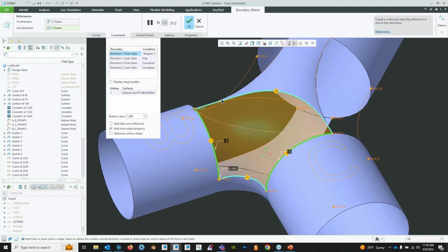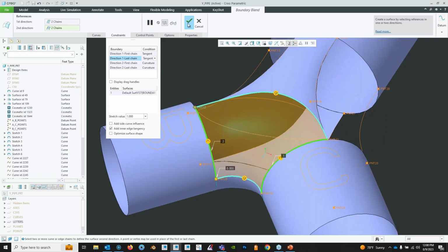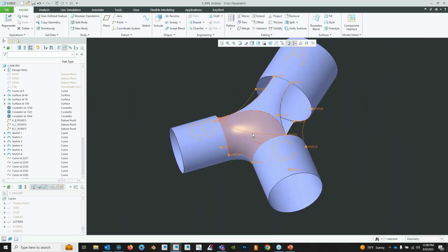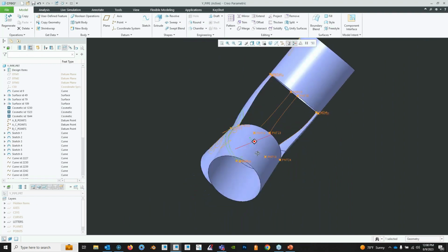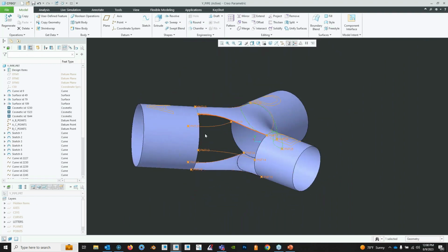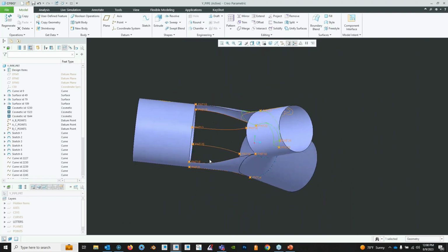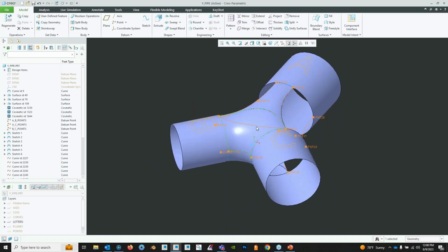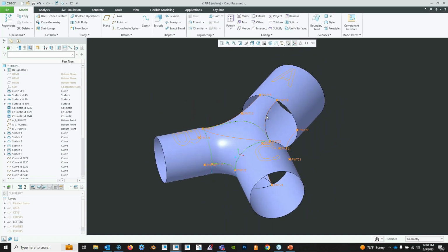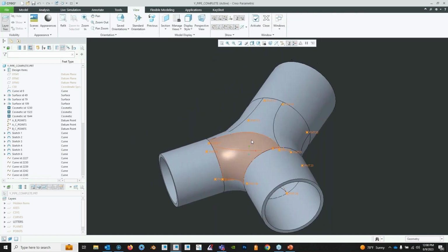It's the top and bottom one. And it'll pick up what surface it's tangent to. And now I got that filled in. And then we would go along and continue to fill in the boundary blends along these sides. And then eventually we can merge all of the quilts together, and then it would give you what you saw earlier, this right here.